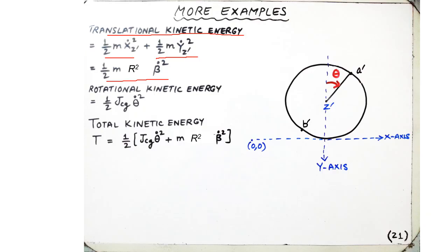Next, we write the expression for the total rotational kinetic energy. And here we need to be a bit careful, as we know that the planet gear A, when it rotates from its initial position to the final position, makes an angle theta with respect to the global y-axis. So remember, whenever we wish to write down the expression of the kinetic energy function, the corresponding displacement variables must be carefully selected, and that must be done with reference to the global axis system.